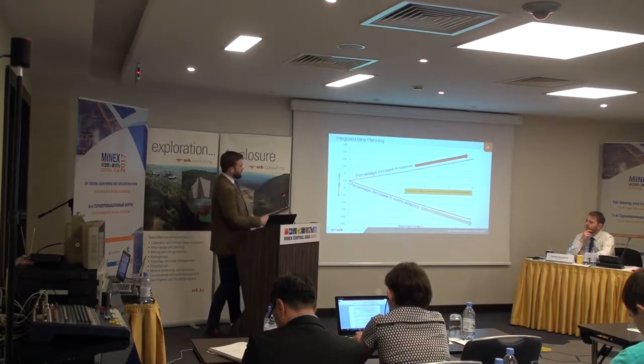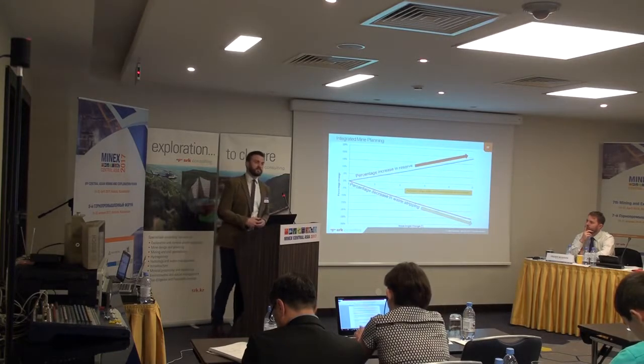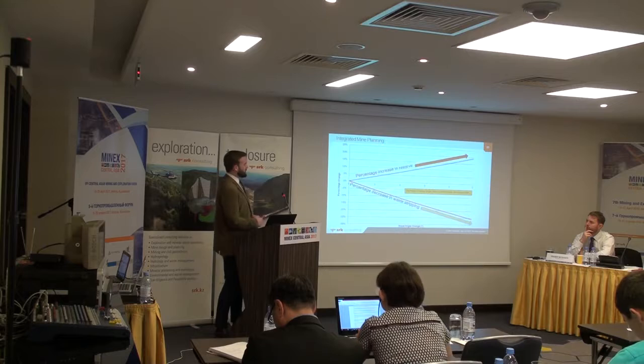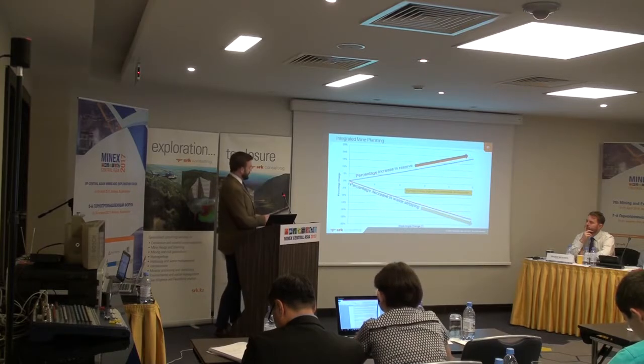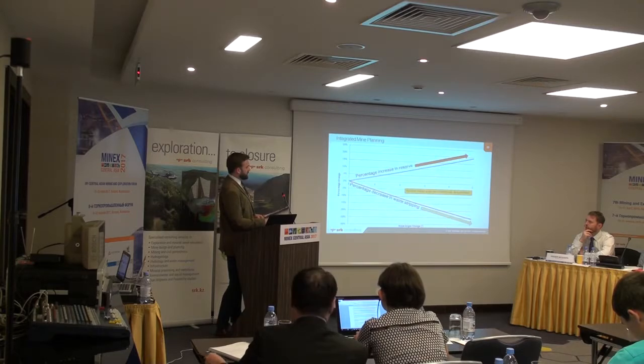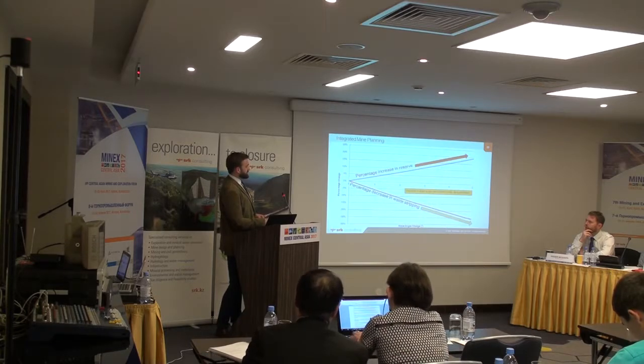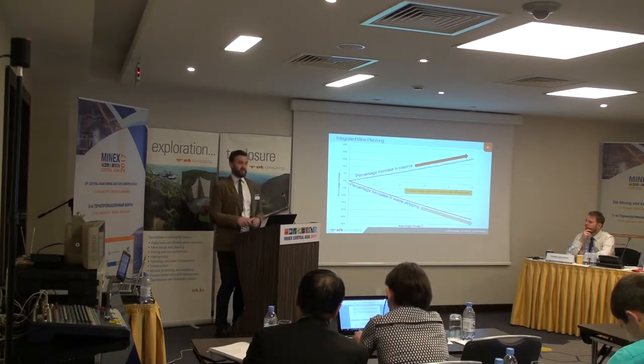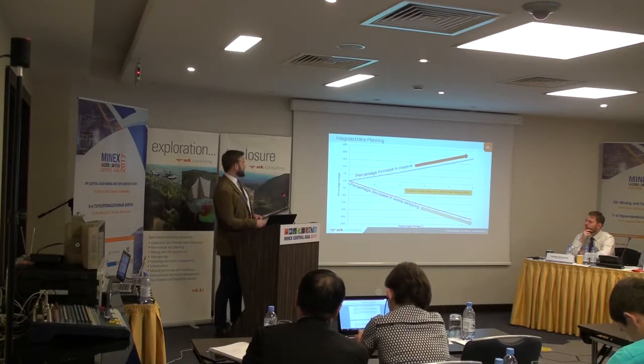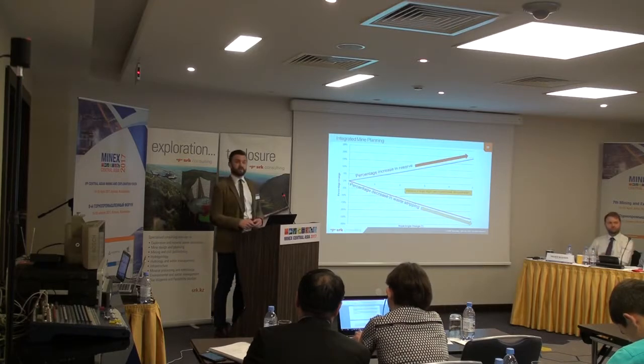And I guess this is the slide that everyone should take into consideration, because any kind of increase in overall slope angle over a conventionally designed slope, as we said earlier, if you can increase the overall slope angle by just a few degrees, these are the kind of percentage increases you're going to get in your reserve, and also the percentage decreases in waste stripping.